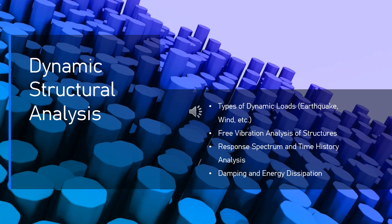4. Hysteretic damping. Nonlinear systems. In some structures, particularly those that undergo plastic deformation, like steel or reinforced concrete structures, energy is dissipated through the cyclic deformation of materials, leading to hysteresis loops in stress-strain curves.